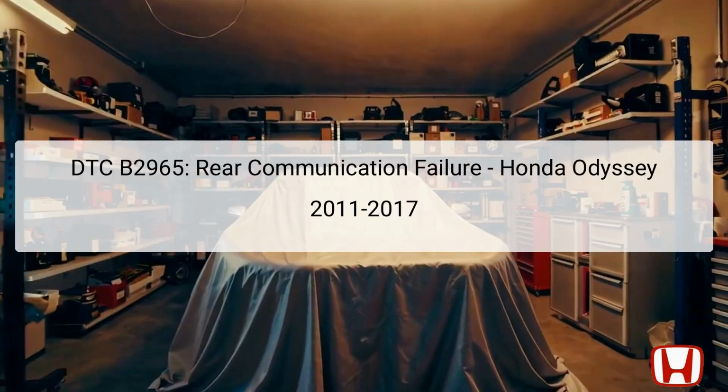The DTC B2965 refers to a rear communication failure in the Honda Odyssey models from 2011 to 2017. This issue typically arises in communication between the rear AC control unit and other components in the vehicle's HVAC system. The main components involved are the rear AC control unit itself, located in the rear section of the vehicle, and the HVAC control unit, located within the driver's dashboard area.